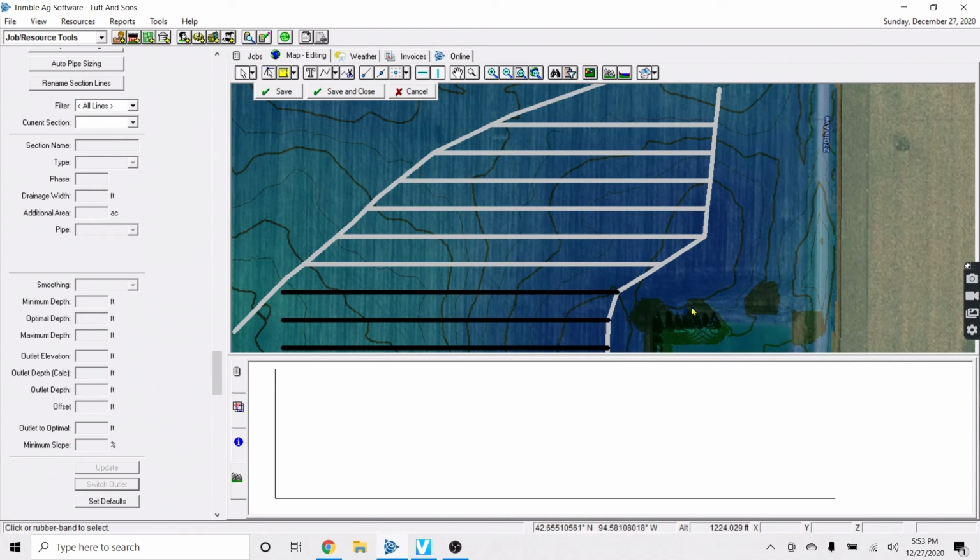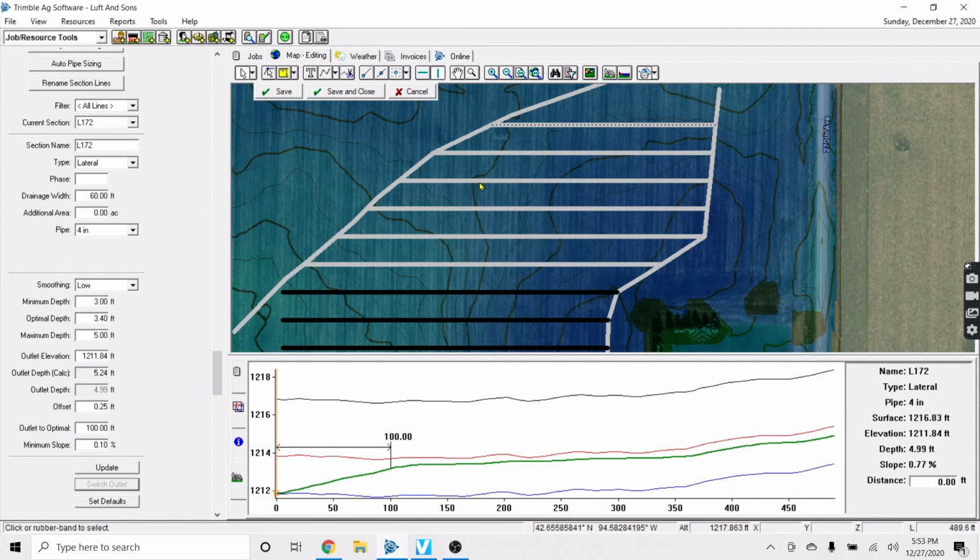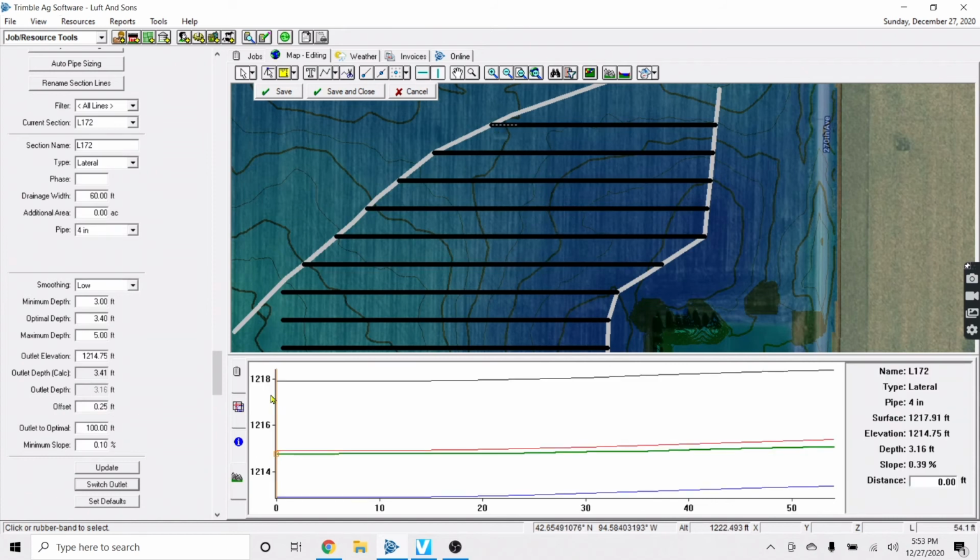At this point, ideal way to do this would probably be do double connections. You'd have less lines if this submain would have turned and went along the grove here, and then we ran lines straight north. But I mean, it's kind of got a funky contour here, so we might be better off to just go the opposite direction and fill it in.